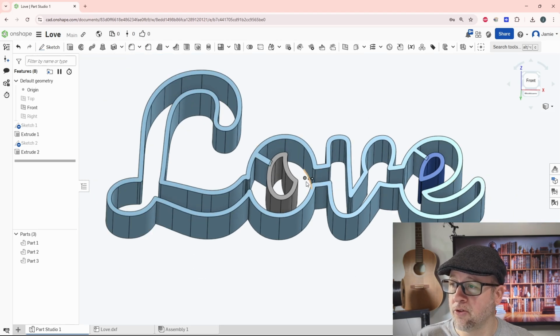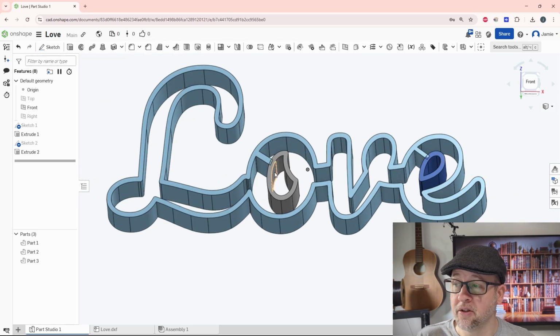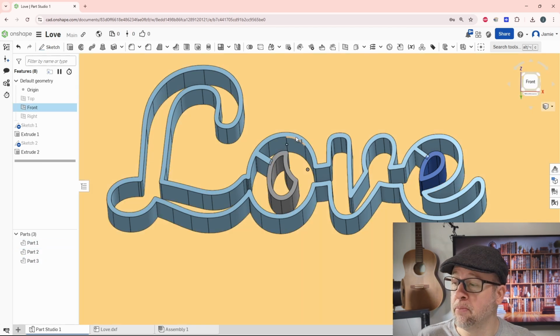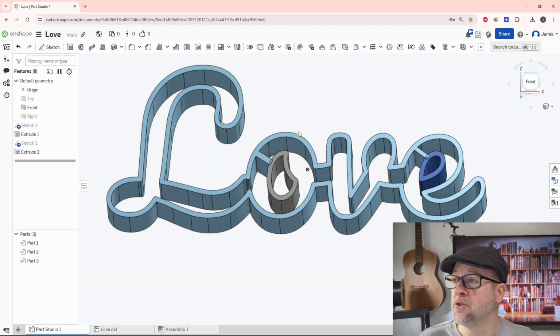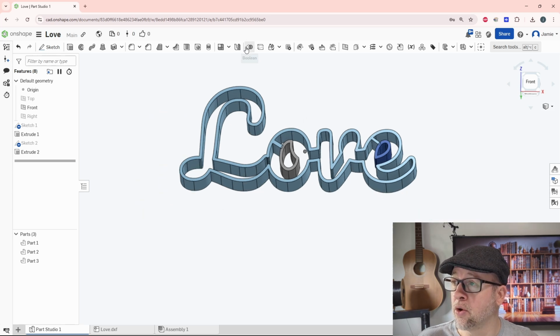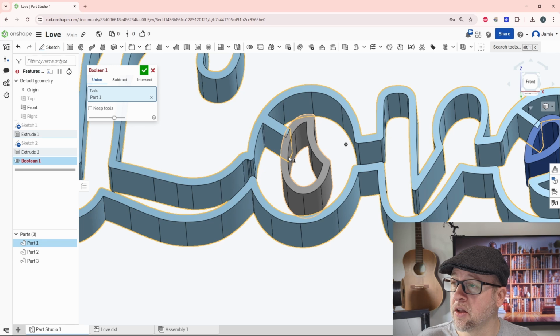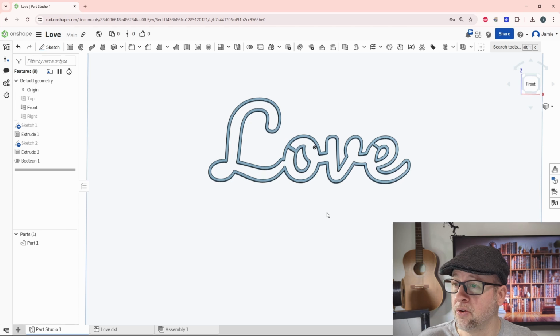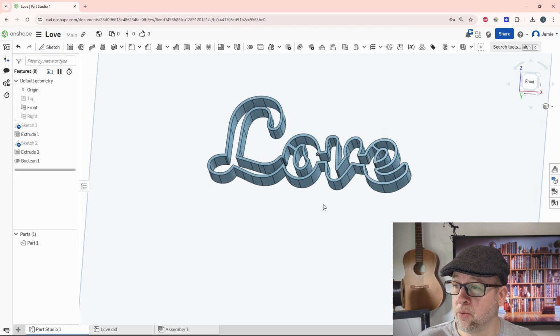Okay, so now it's not combined yet. We have 3 parts here. So we got part 1, 2, 3. To combine them, spacebar to get out of that. To combine them all together, we're going to go to Boolean and go to Union here. All right, click on this guy, and this guy. Okay, now we got 3 parts in here. Click on green check. And notice they're all good now. Now we're all good to go.